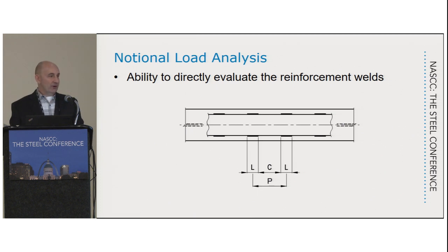Okay, now this is an important one. It gives you the ability to directly evaluate the reinforcement welds. When you weld that plate to the flange of that member, you need to know what load is in that plate, or what load you're going to design for the shear flow. We'll talk about that in the next section.